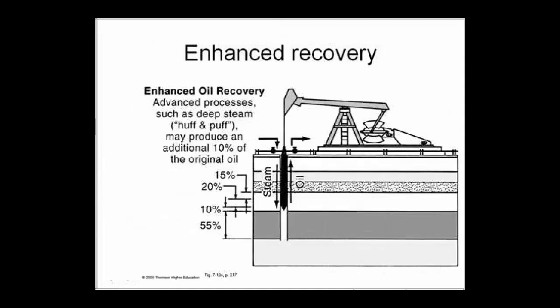Most modern systems now will extend to what's called enhanced recovery, and this incorporates steam or some other fluid, but typically steam is the most common one, to reduce the viscosity of the oil and enable it to flow more readily and to enhance its extraction. And also there's some slight pressurizing of the fluids that may cause them to migrate to the pumping area as well. So the overall recovery process is not as efficient as you might think because of the difficulty of getting all the oil, or as much oil as possible, out of the myriad voids, fractures, cracks, and other openings in the rock formation in the reservoir.